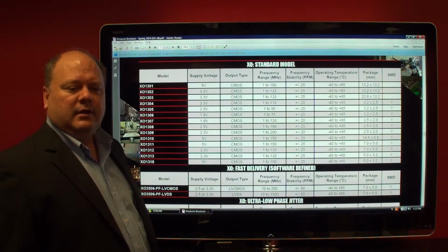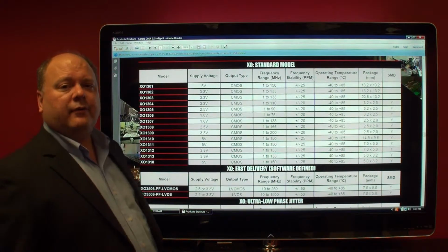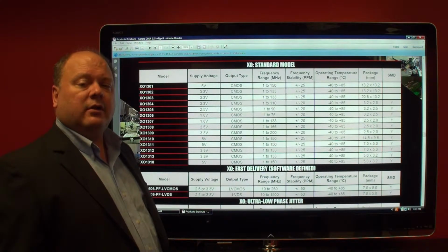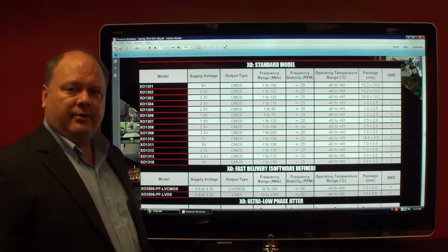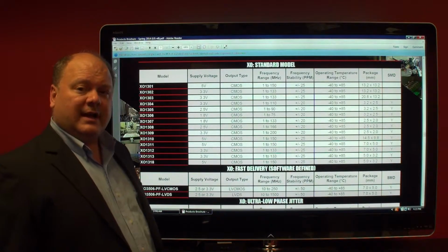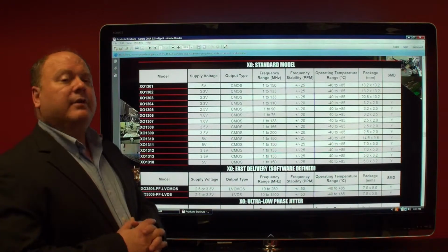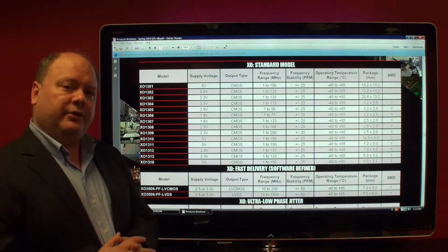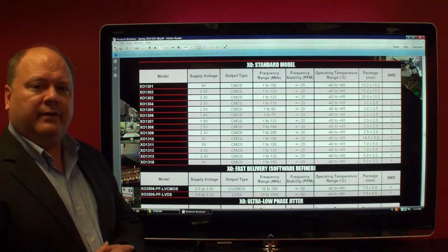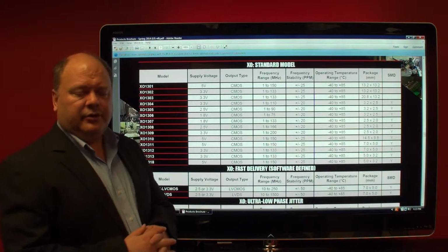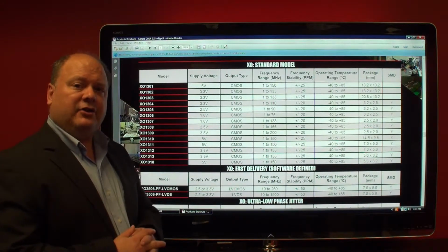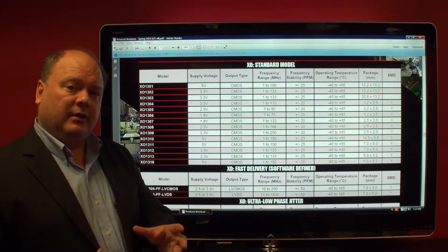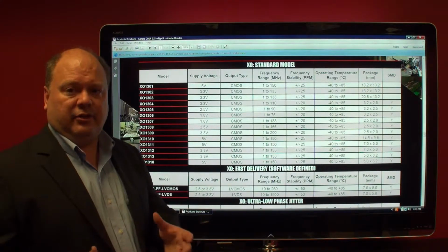Good afternoon. Today's discussion for the 2014 Dynamic Engineers product brochure is with respect to the category of clock oscillators, or XOs. XOs, or clock oscillators, are devices that do not have a voltage control function. There is no frequency versus voltage functional pad or pin signal function. So the customer cannot change the frequency by changing a voltage. The clock comes in with a certain tolerance of frequency and they cannot change it.